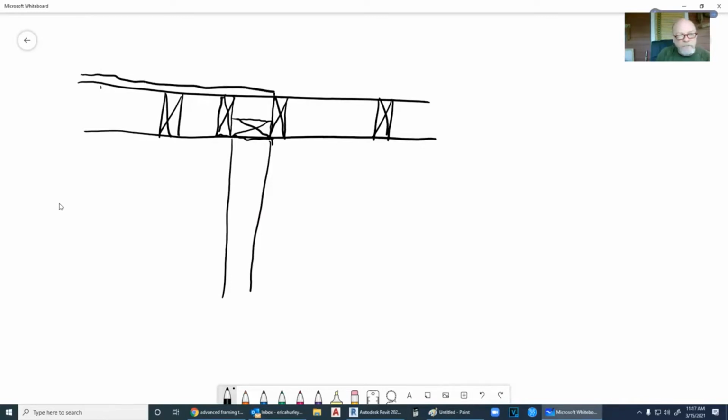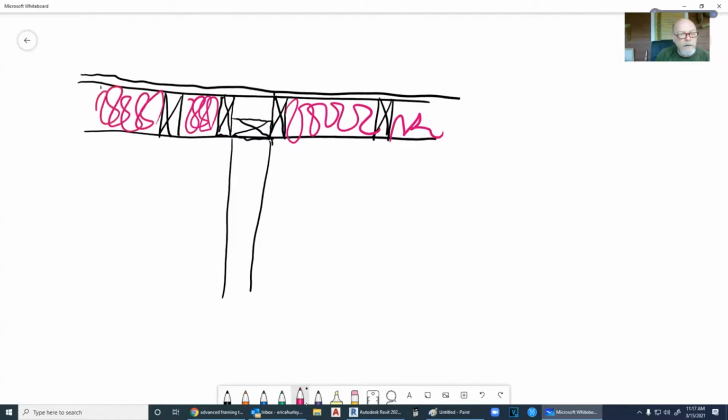We go to put our sheathing on. Bam, we have just closed this hole here, and there's no insulation. Insulation people come in here and they put the insulation here. And then this, there's no insulation in it. So we have cold air that could infiltrate this, which means that we have a suction of cold air that's trying to pull warm air. Remember that warm air goes to cold air, and it's like a big old suction. It just sucks the life out of us. If we've got air conditioning going on in here, the opposite effect is going to happen.